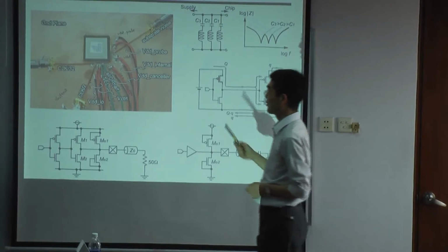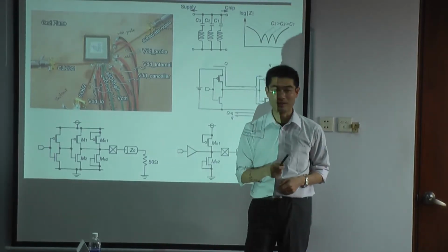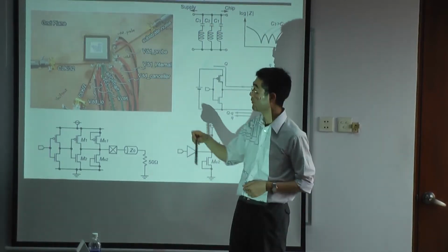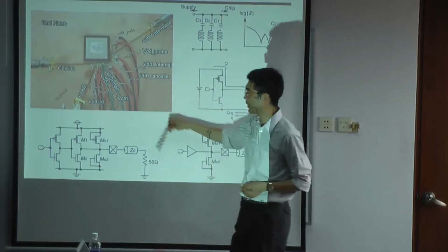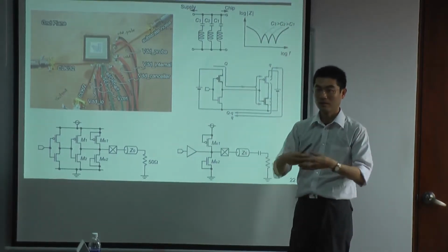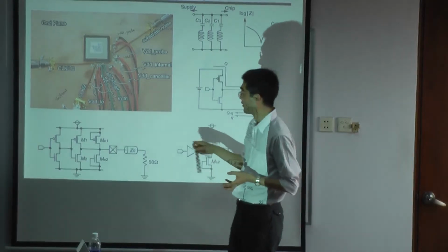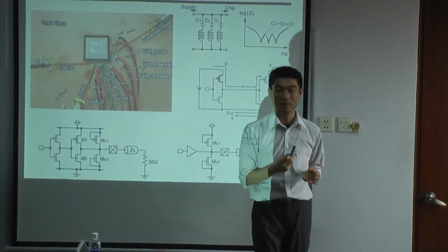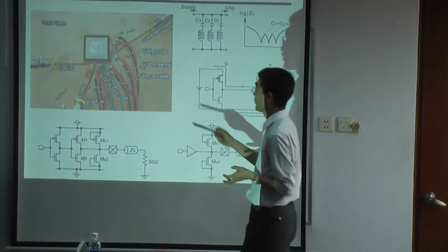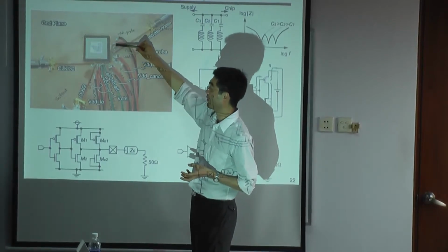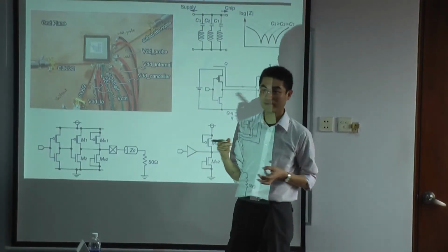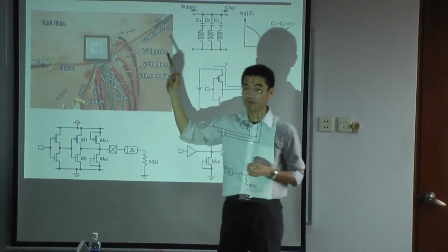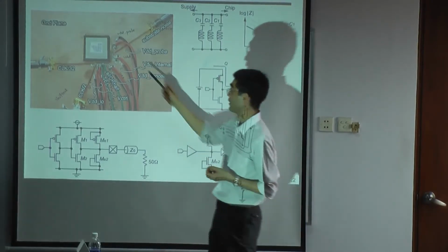Here, in order to stabilize the power supply, we want to have an ideal power supply island. At the end of this line, we will have an ideal power supply. But we have a very long wire, which has a very big inductance, so this island is very noisy. So we want to stabilize this island, and we put many types of capacitors between this island and ground.